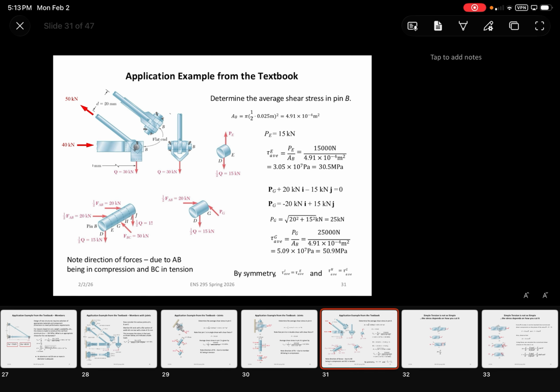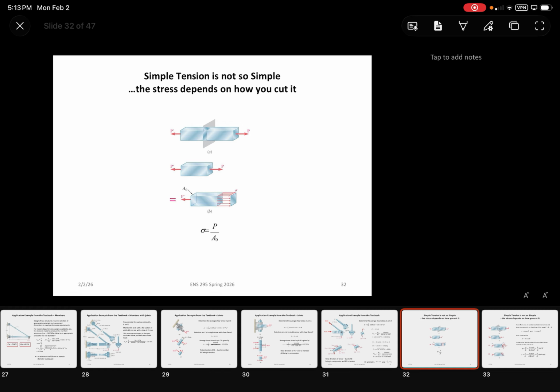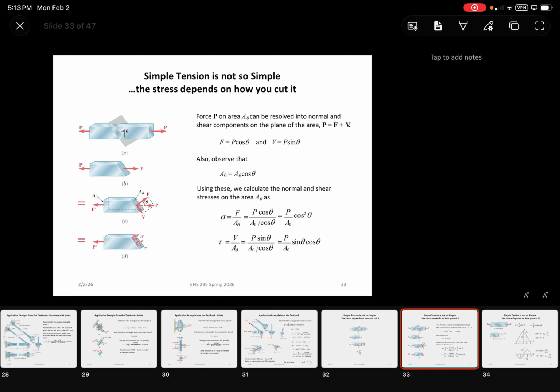All right. Now, continuing from last class, we know that stress is equal to force divided by the cross-sectional area, but that stress is ultimately dependent on what area you're really considering. It's all dependent on the orientation of the plane, how you cut a certain section through a particular member. One such example is if you cut a plane through an oriented rotation. For example, this could be something like a weld line, like if you're connecting two elements together through a weld and transferring axial loads, that plane could be a representation of a weld that's inclined.